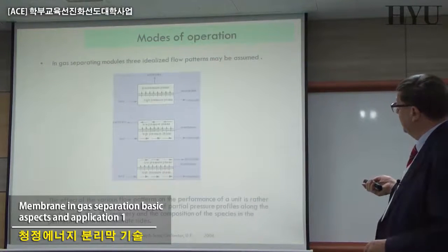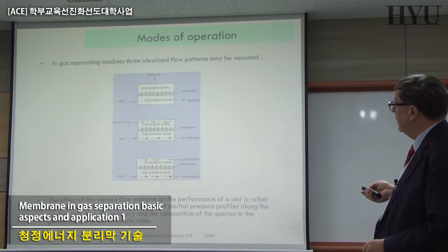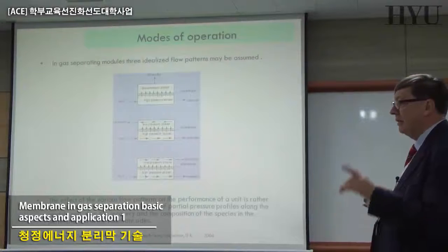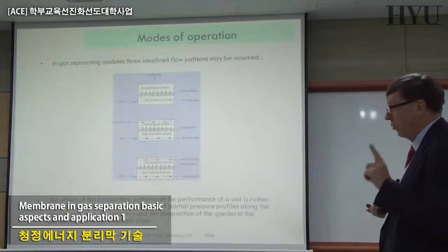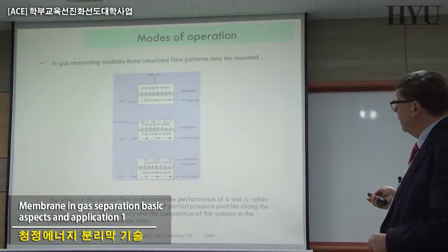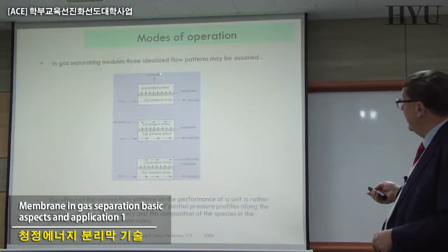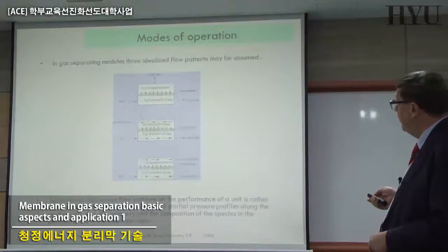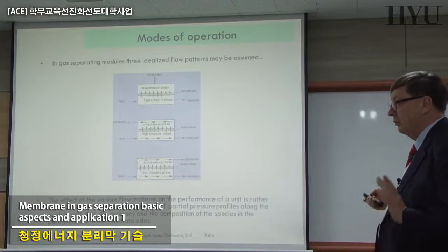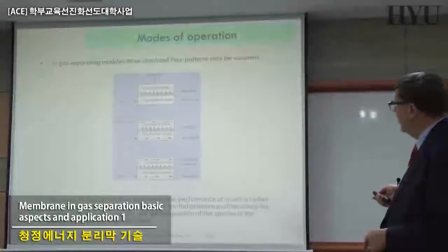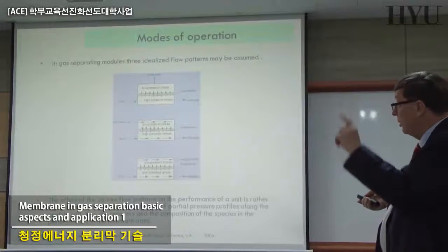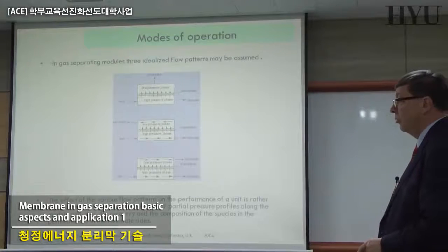Here is the case. First of all, we already said we can work with a single module, at least as in liquid phase, exactly the same, in three different ways. Here is dead-end flow. You have your feed, and you just pressurize it normally against the membrane surface, and you have the permeate going across and the concentrate moving out.